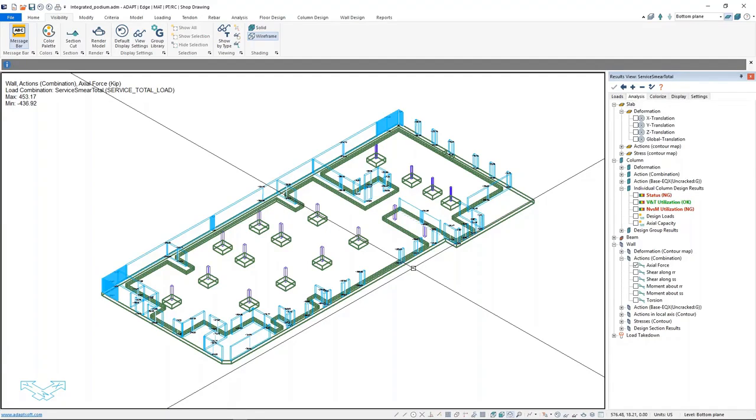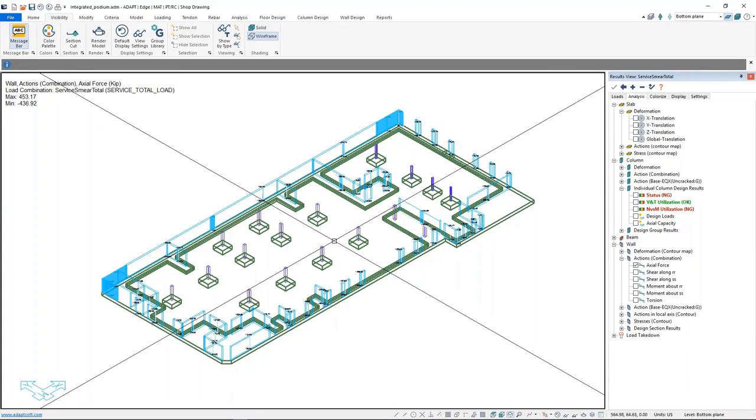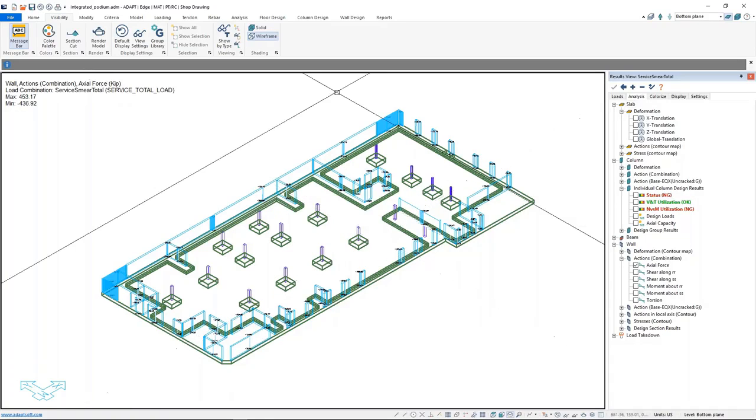Because I still maintain both load sets, I find that in almost all cases the smear load is governing. This is just anecdotal evidence based on this configuration, so I don't think there's any specific guideline. It's probably prudent to do both, but I see a lot of people get away with the smear loads as well. Let's move to the next question.